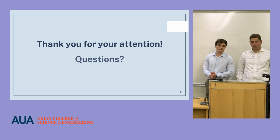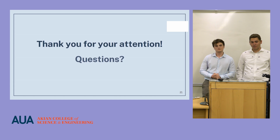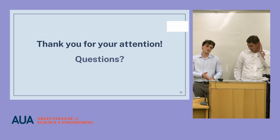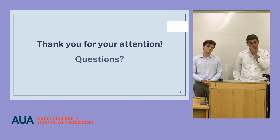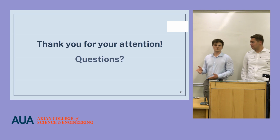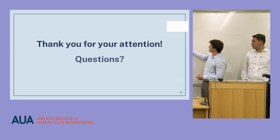You know, right now what you're doing, if I'm not mistaken, your balloon is a single point mass with a thrust attached to it. All forces are acting at the CG, right? Yes. However, in a balloon, all forces do not act at the CG, especially your thrust. So we might have some sort of imbalance in that case. It might be tilted like this.